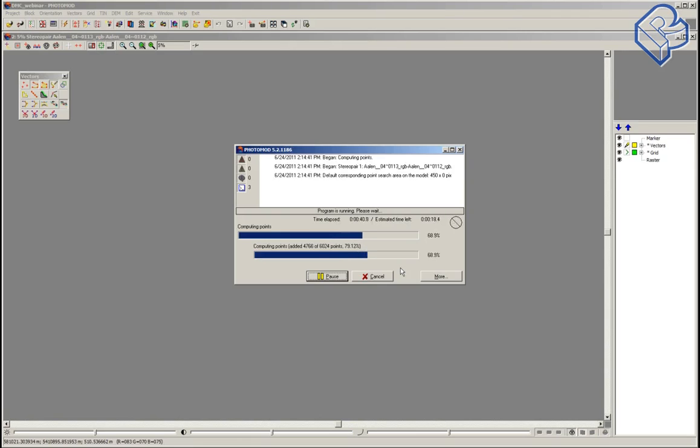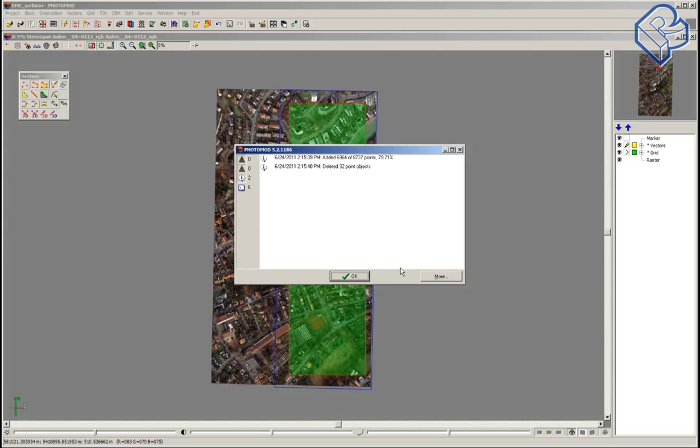For example, if we work with forest or with mountains, we can choose one of these presets for one part of the project, and for example, in the city, we can create another grid and use another preset here. And after filtration and editing all these parts, we can create the whole final DEM this way.